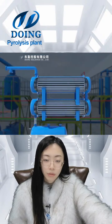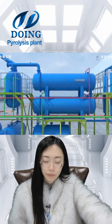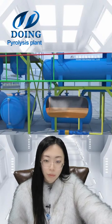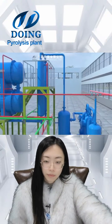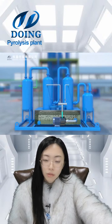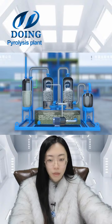And then it comes to the third condensation system, the horizontal condensers. They have 37 tubes inside to spray out the gas and get more contact with the condensation water. All of the gas that we can condense will be condensed, and some of the gas that cannot be condensed is the tail gas, which we will send to the purification system.